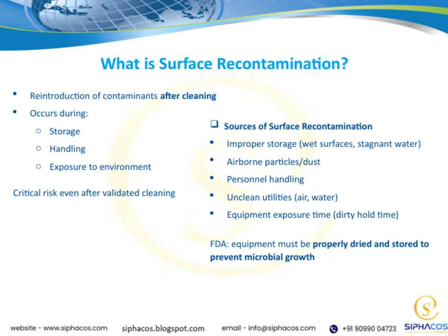Personnel handling can inadvertently recontaminate surfaces if proper hygiene isn't maintained. Unclean utilities, such as contaminated air or water, can also be a source of recontamination. Lastly, the length of time equipment is exposed, what we call dirty hold time, matters a lot. Longer exposure increases the risk of microbial buildup. The FDA emphasizes that equipment must be properly dried and stored to prevent microbial growth.